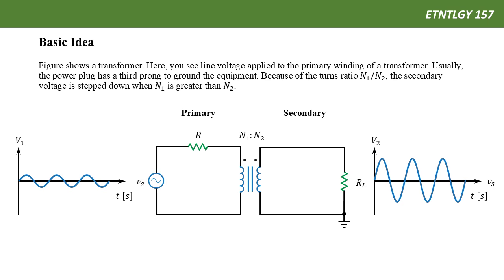And there are a few notations, such as above the transformer schematic symbol, you will see N1 : N2. The N here means the number of windings, the number of turns for making that inductor. And N2 is the number of turns of wires, the loops, for the secondary inductor. This is one of the most important factors that can affect the kind of transformer. Whichever side has more turns, that side has higher voltage.